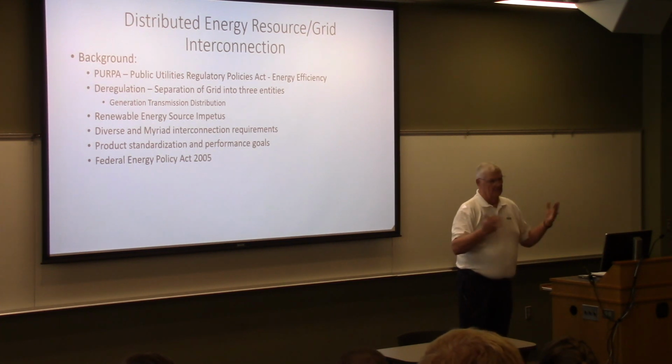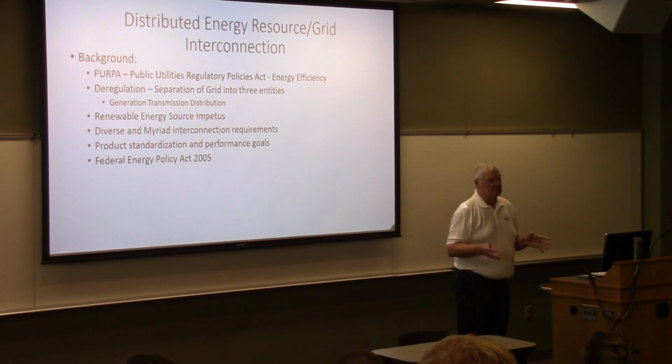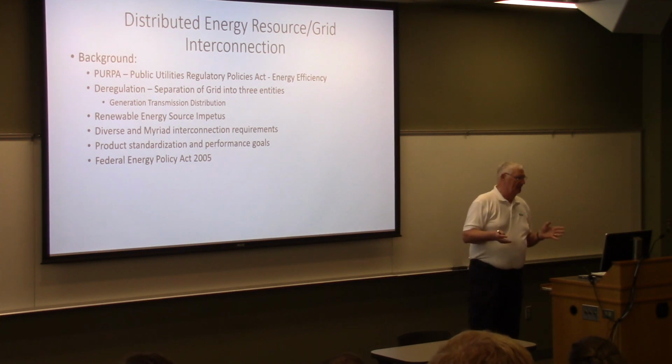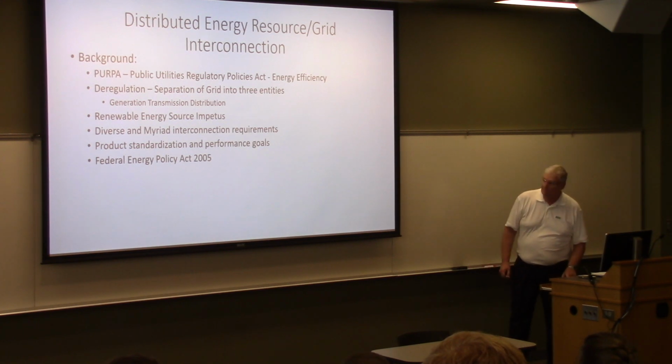So if I have a 100 kW solar farm, and I tell the ISO I'm going to come online tomorrow, it's going to be a sunny day, so I'm going to bid in to provide energy, he's going to say, okay, I'm going to count on 25 kilowatts from your 100 kW station, because that I can pretty much count on being there. If I get more than that, hey, I'm ahead of the game, but I'm going to count on that. You're going to get paid for all you produce, but he's only going to give you an allocation of 25%, because that's the reliability of it.